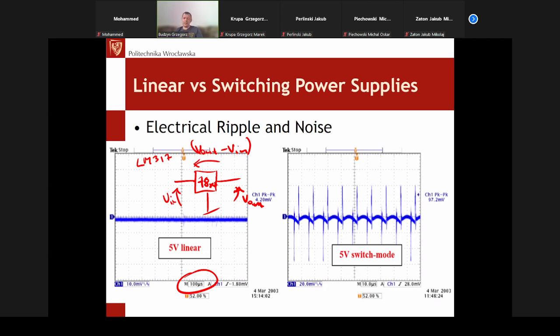At low current, low dropout may require as little as 50 millivolts. For high current, low dropouts usually are about 200, 300 millivolts. So that's the difference. And if you intend using linear regulators to get fine output voltage, then be careful. So try to have this in mind, that low dropouts are advisable here.